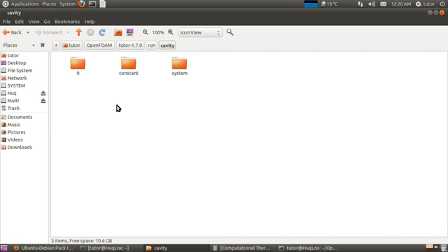This is the typical first example of OpenFOAM. A general case in OpenFOAM, this folder is generally called a case. So in this we have the example of cavity. So our case is cavity here. The general case in OpenFOAM by default consists of 3 folders: 0, constant, and system. The 0 folder always contains the information regarding the initial conditions and boundary conditions of the problem. The constant folder contains the files having the information about the properties which are always kept constant during the whole time of simulation. For example, the viscosity of your fluid or something like that, density maybe.